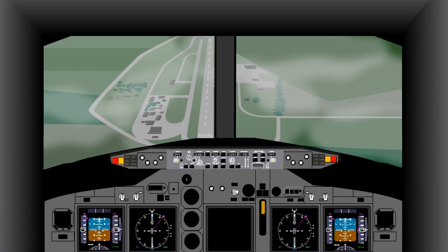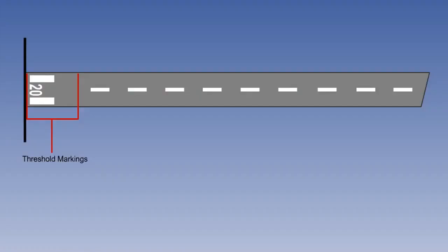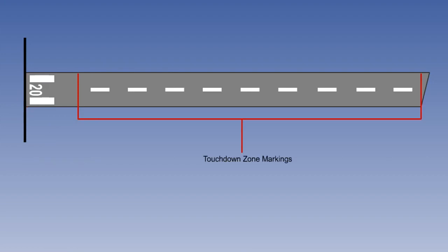In order to continue the Cat 1, APV or non-precision approach beyond the applicable decision height or minimum descent height to a landing, the pilot must be able to see enough of the approach to landing area to complete the landing visually. This visual scene is called the visual reference and has as its minimum either the physical surface, runway markings, or runway lights. The physical surface that forms the visual reference is either the runway threshold or the touchdown area.